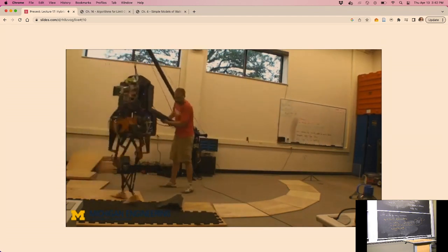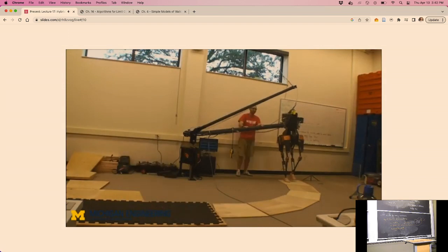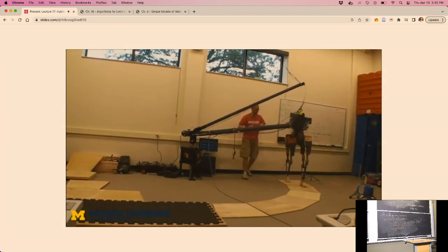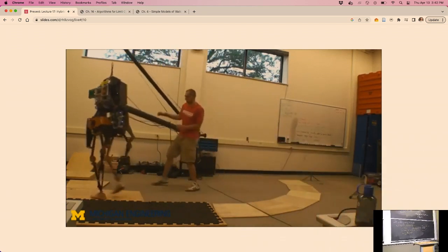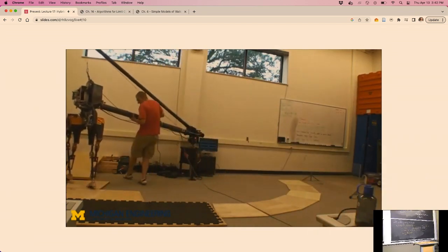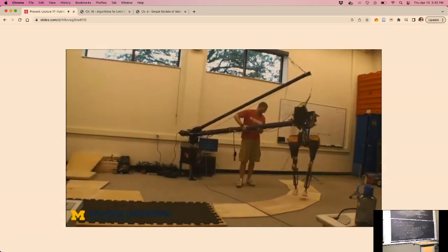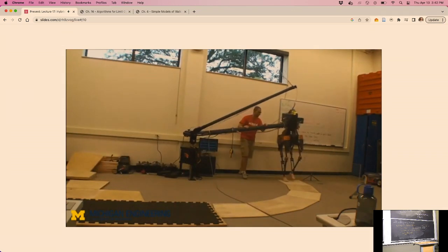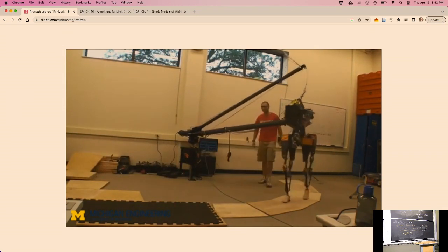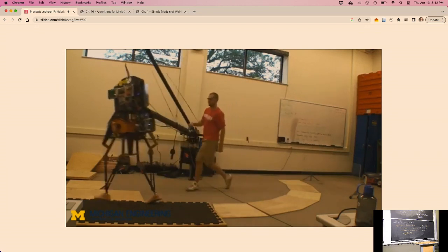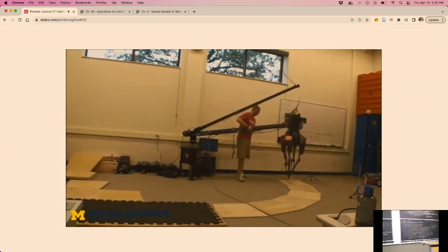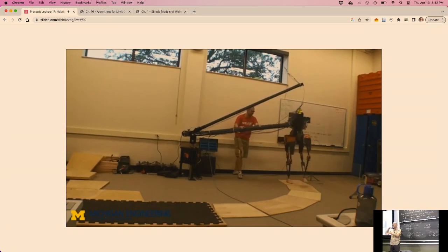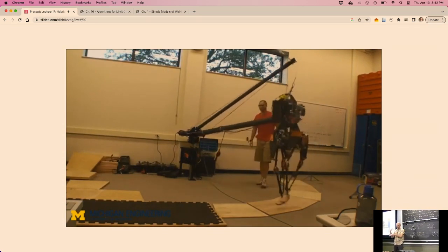It's basically you've made a clockwork man, right? Where it's just, as a function of the bottom leg angle, there's a prescribed set of angles for the rest of the robot, okay? So no matter what that is, you just walk it forward or backwards. That's what orbital stability looks like. So the controller's active the whole time, even as he's bringing it back? Yep. So what it's doing is saying, as a function of my, let's say, ankle angle, what are all the other joint angles? And you get this beautiful stability out.